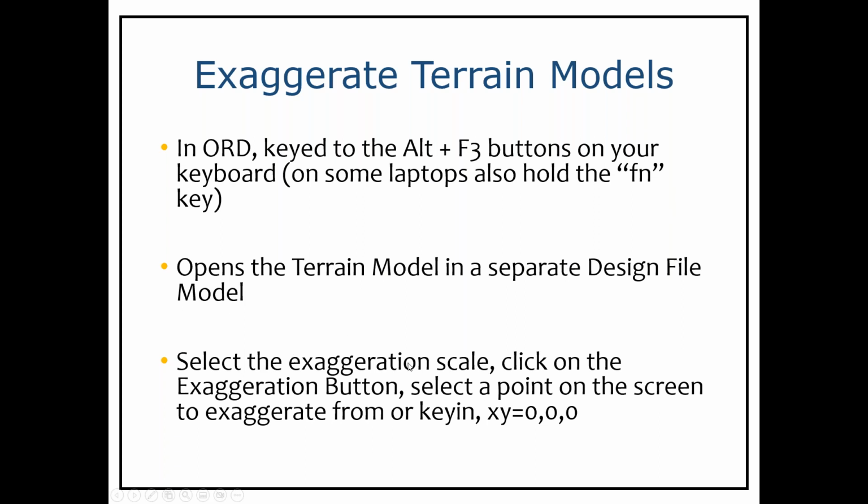Then you can select the exaggeration scale, click on the exaggeration button, and select a point on the screen to exaggerate it. Or if you want to key in from a specific elevation to see heights and differences, you can key in XY000, for instance, to do that.